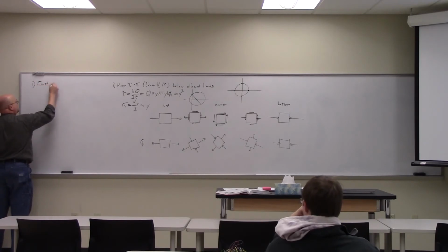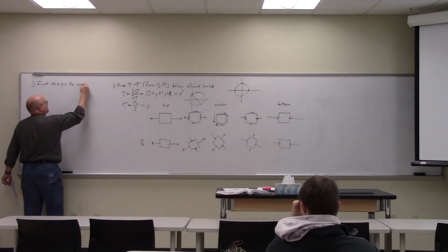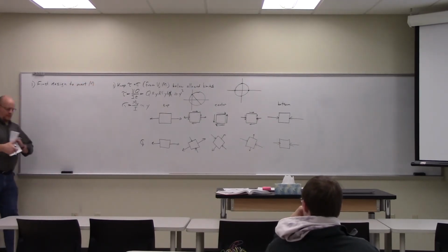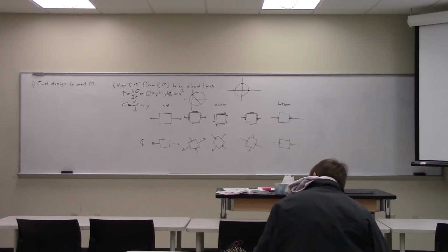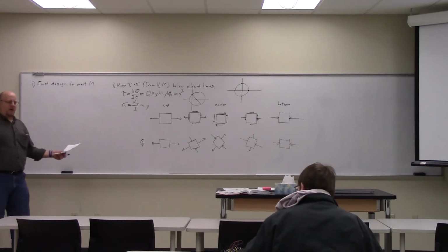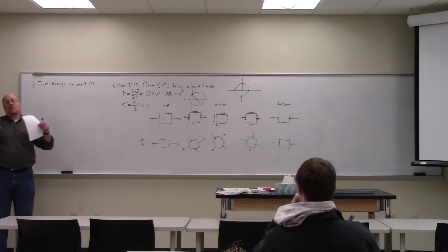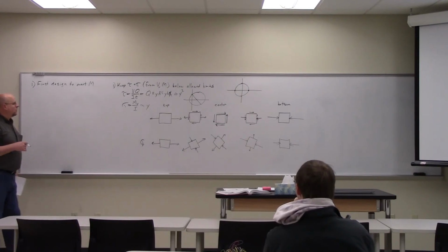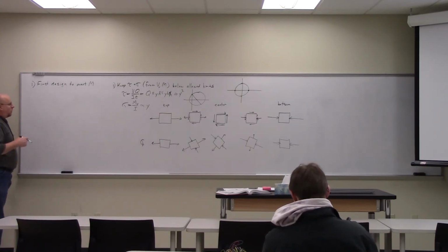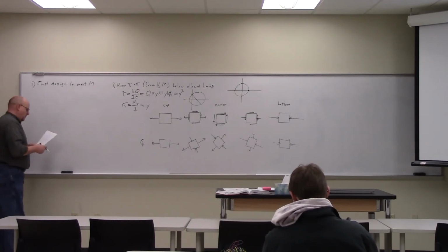We will first, in most cases, design to meet the bending moment. Most beams are fairly long. That's the purpose of the beam, to have a long breadth of distance that's covered, that's supported. And so since you've got such great distance, the moments tend to get fairly large. Right? So in most cases, for long beams especially, we want to design first to meet M, and then we'll come back and check and see if the design that works to support M can also support V.